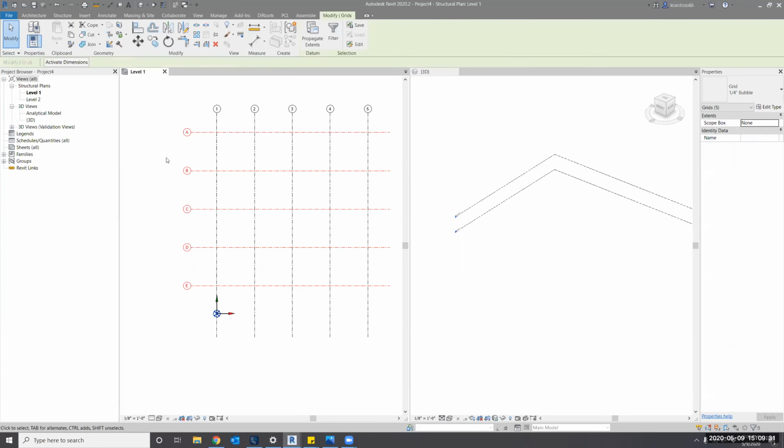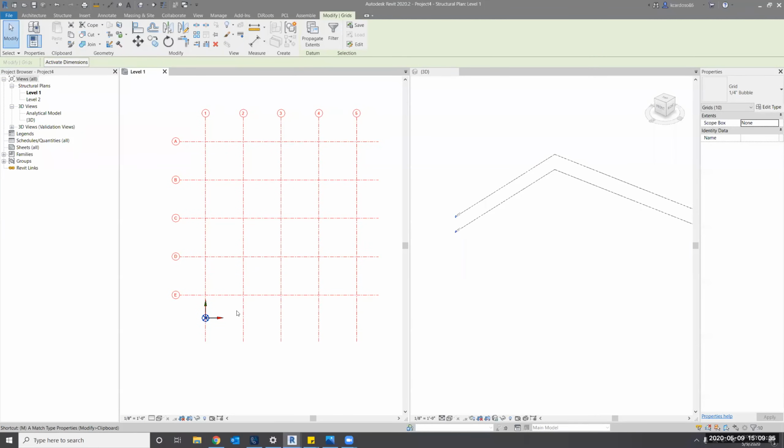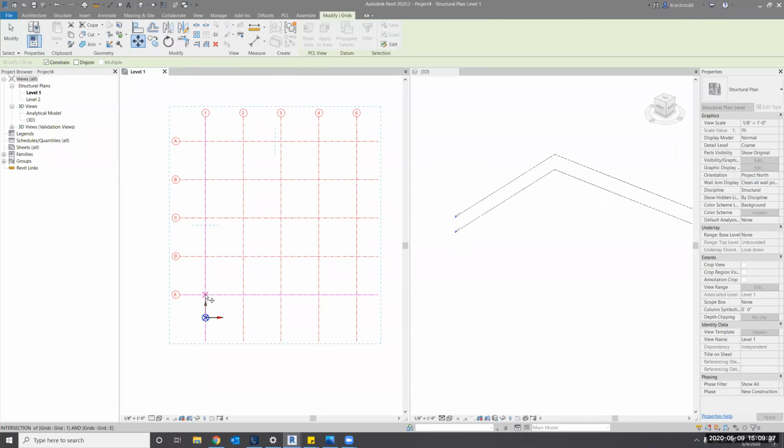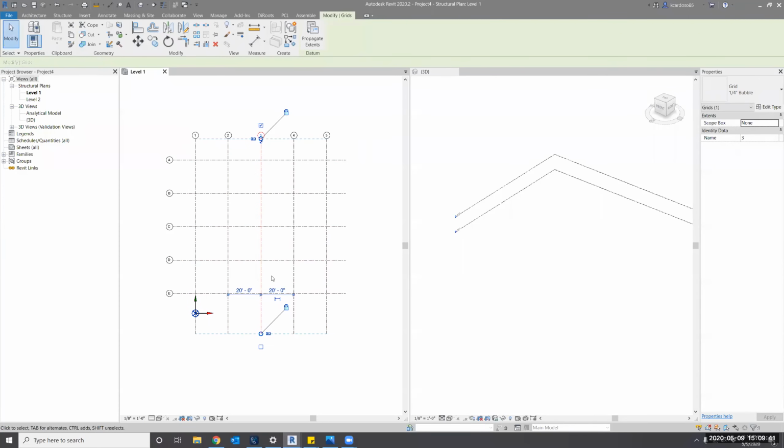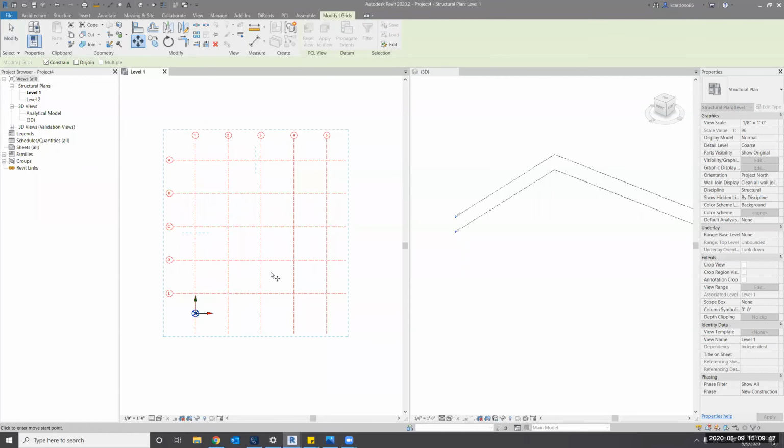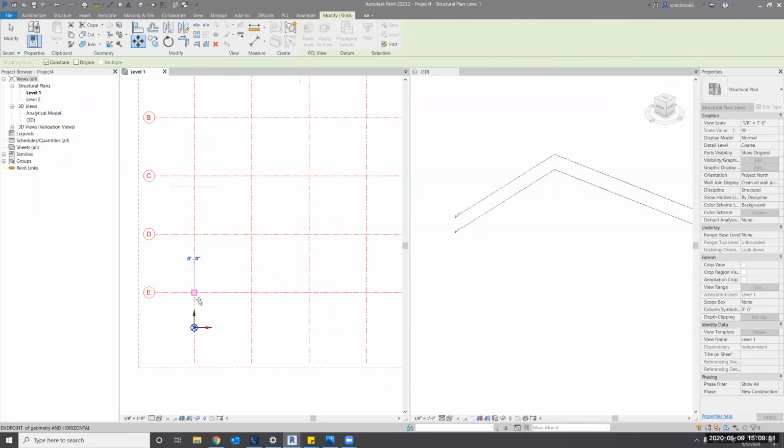All right, so let's make these grids a little bit more organized. I like getting organized with my grids because I think of this quite literally. So let's move. What I did there is I selected one grid. I hit select all on my keyboard. And then I hit move, MV, and I hovered over the bottom left intersection, and I just physically moved it to that point, okay?